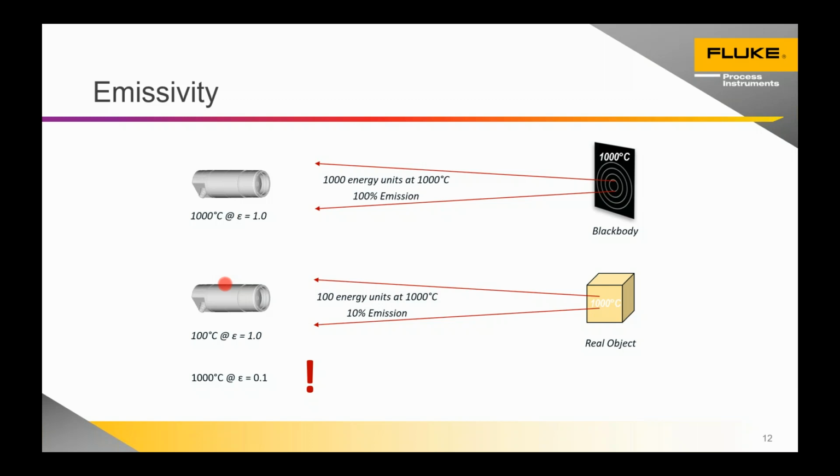Last part to that. Generally, if there was gas and it was an influence, you would see it as an attenuation of the reading, unless the gas was significantly hotter than the object. And we have sensors that are actually optimized for measuring gas, so we're able to measure hot CO2 and hot NOx, hot carbon dioxide. But generally, something would attenuate the reading, if at all.